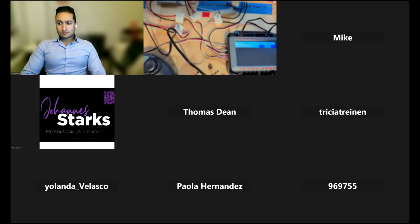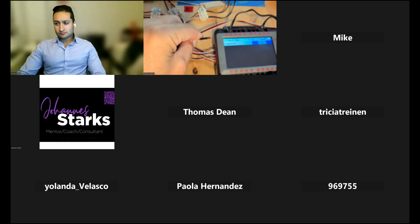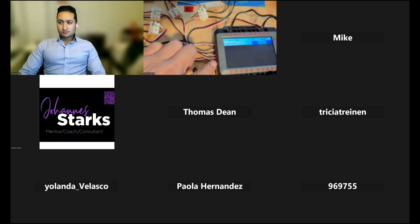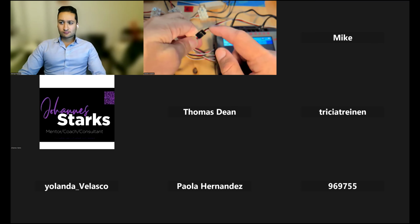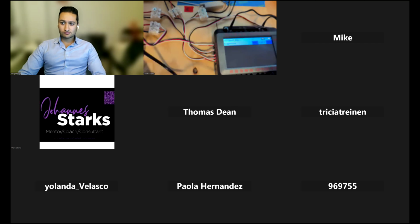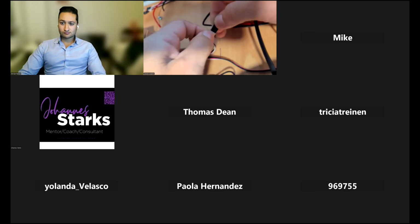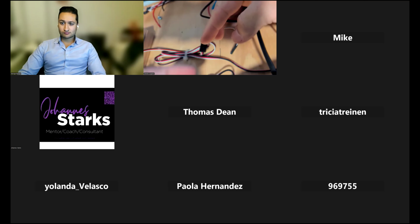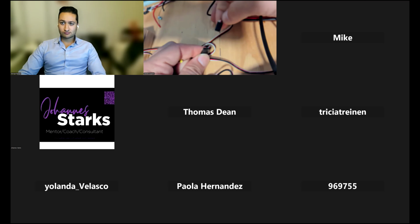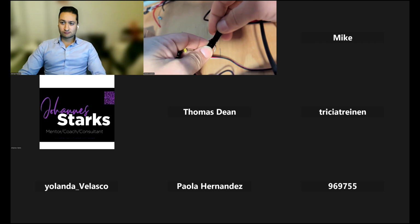And then just on the hardware side, to kind of go over that, I have this servo extension wire that is plugged into port A over on the side. These 3 wire ports go from A to H. Notice that's a male pin connector. You need to have a wire that has male pins to plug into that port. And then on the other end of my extension wire, I have header pins because the end of my extension cable is a female connector. And then my servo that I'm plugging in is also a female connector. So there would be no connectivity there if there's no way to plug those in.